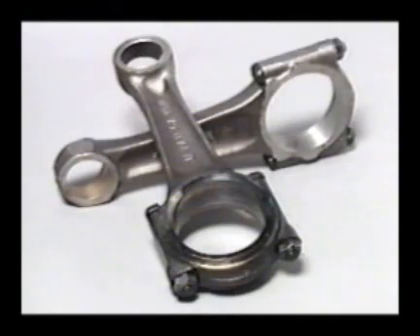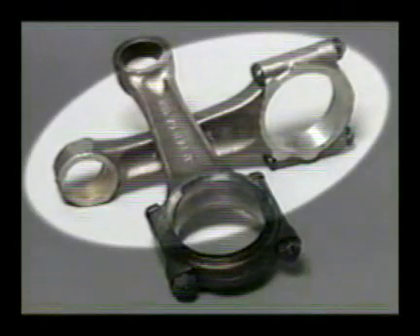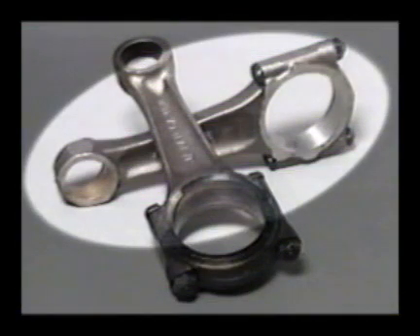From their appearance, which of these connecting rods do you think still has adequate material strength to do its job? The tempered colors on the rod in the foreground indicate it's been too hot, and you correctly selected the other one. We should always be suspicious of parts that show evidence of having been too hot.